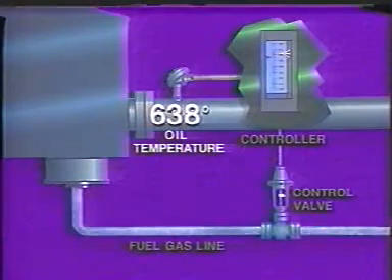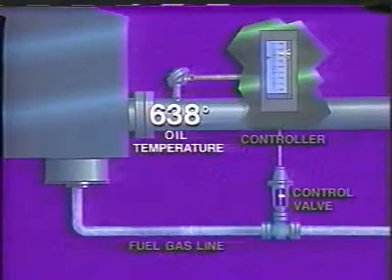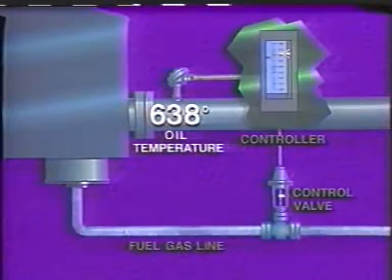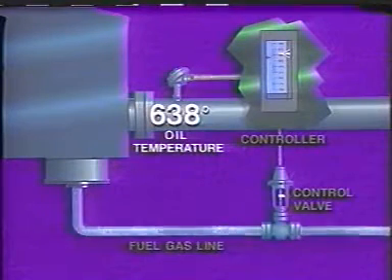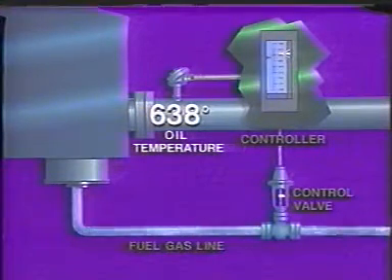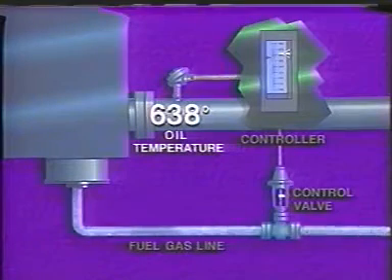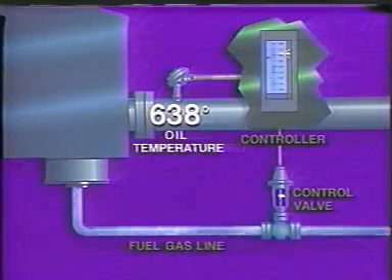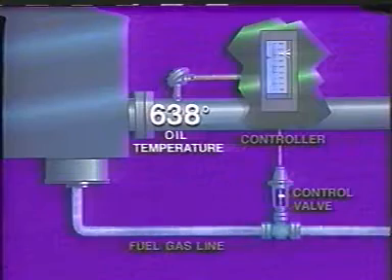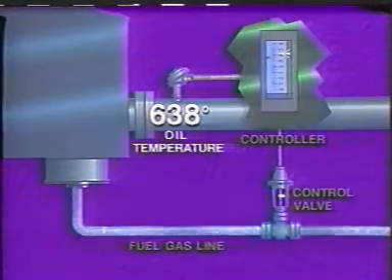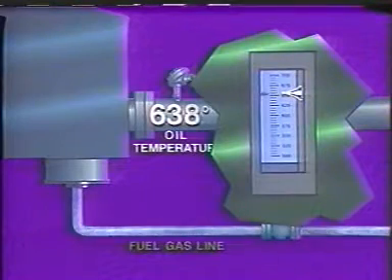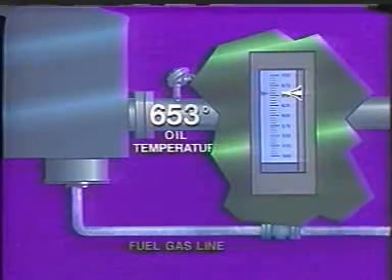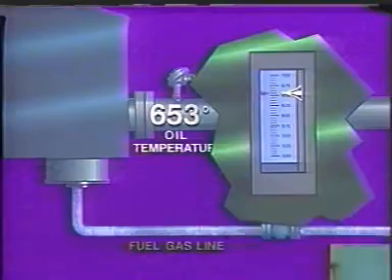This change in temperature is sensed by the thermocouple and transmitted to the controller. Again, the controller compares a reference value with the transmitter's measurement signal. If the 2 values are the same, the controller continues to send the same signal to the control valve. If the 2 values still do not match, the controller again changes the signal transmitted to the valve. The controller continues to adjust the valve until the controller's reference signal and the signal from the transmitter are the same. Let's review these control loop actions.